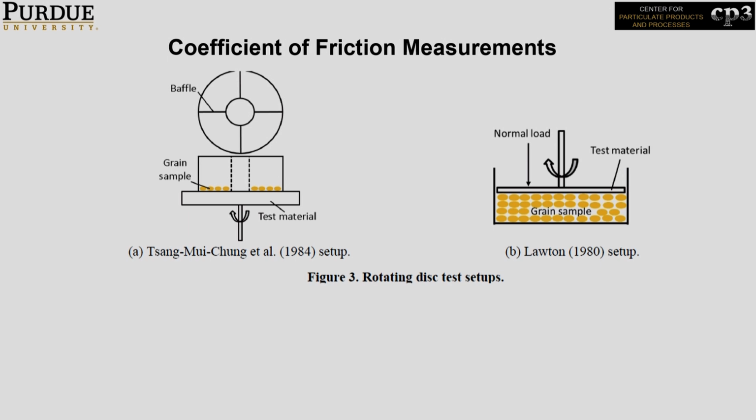And again, very similar to the shear setup, there's a baffle that goes into it, and when the baffle moves over the grain surface, you measure the friction. Okay. So there are tons of friction measurement setups that you can develop and use, but there will be some disadvantages. Again, the same disadvantage, you will see movement or rolling of materials that will affect your friction measurement.